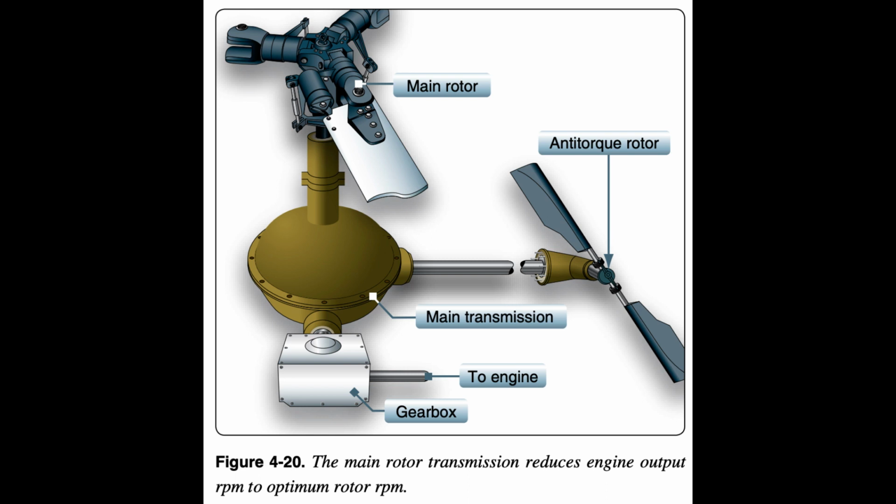Piston-powered helicopters have a means of engaging the clutch manually, just as a manual clutch in an automobile. This may be by means of an electric motor that positions a pulley when the engine is at the proper operating condition, oil temperature and pressure in the appropriate range, but which is controlled by a cockpit-mounted switch.